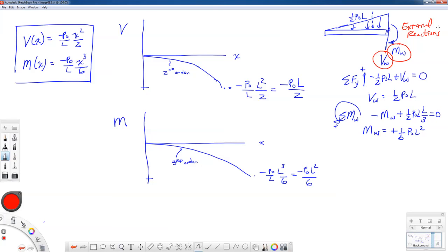They will only be the value of the internal shearing force and bending moment if you draw them according to the positive sign convention for the internal shearing force and bending moment. They'll have the same magnitudes, sure, but they may not have the right sign unless you set these reactions up to have the appropriate signs to make everything work out.